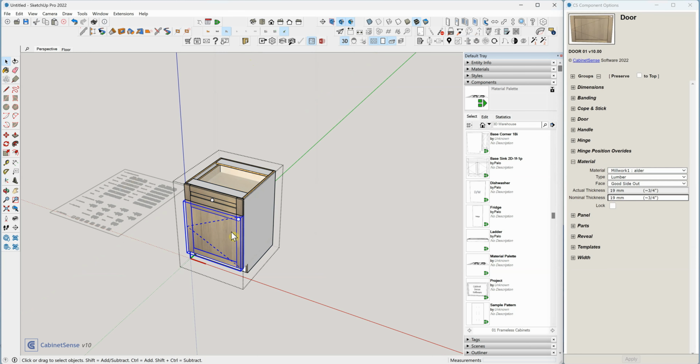for our island. And I'm going to go down to the finishing group, and I'm going to say that our MDF is going to be colored white. So this has done a couple things for us. We know the material is MDF. We know we're going to spray it white. And on our bill of materials, we will actually get an area, square yards or square meters, of the surface area to paint. So we can use that to help us estimate.